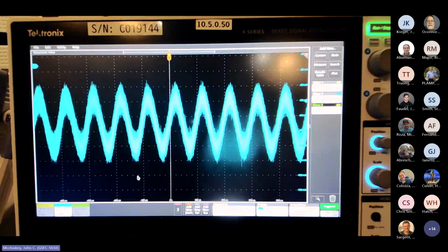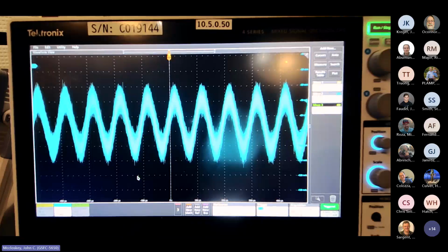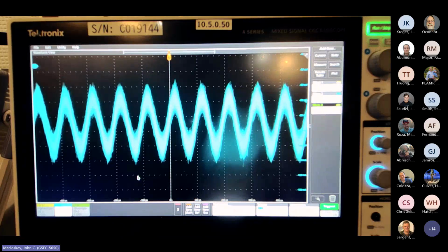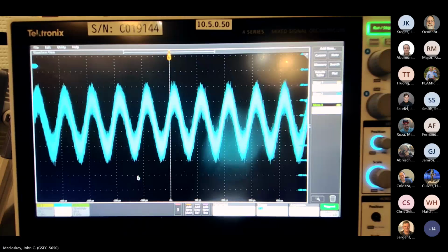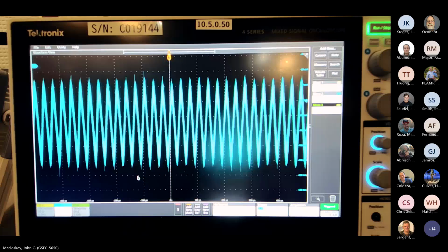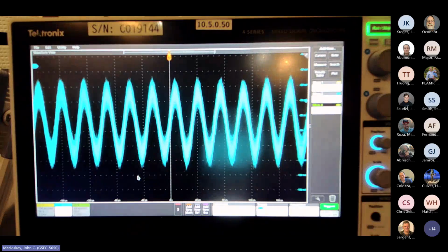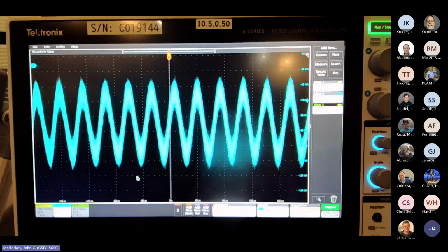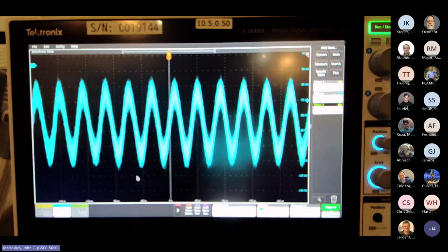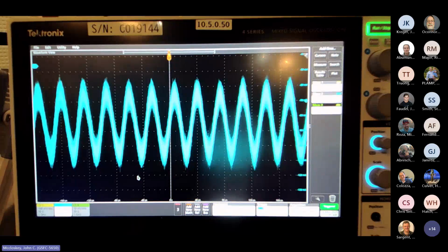Going up to 30 kilohertz, our reading is about 11.8, 11.9 milliamps RMS. Our frequency changed, and the signal level has gone up to like 14.3, which is right in line with what I had on Monday. It should be, since this should all be very repeatable.